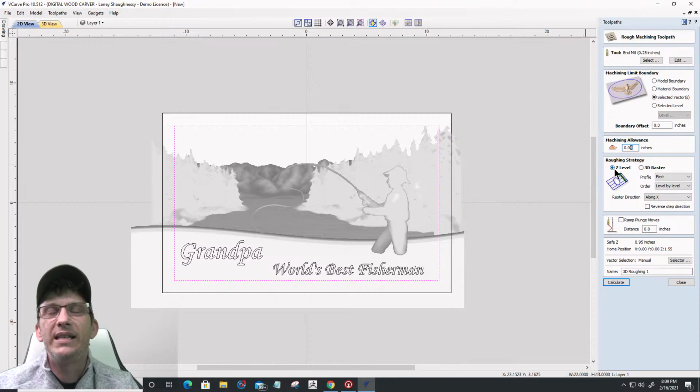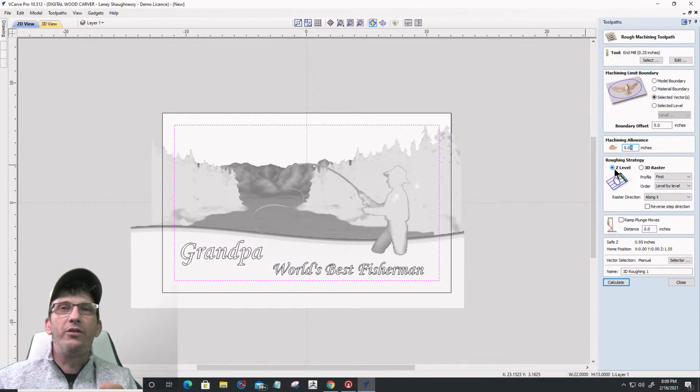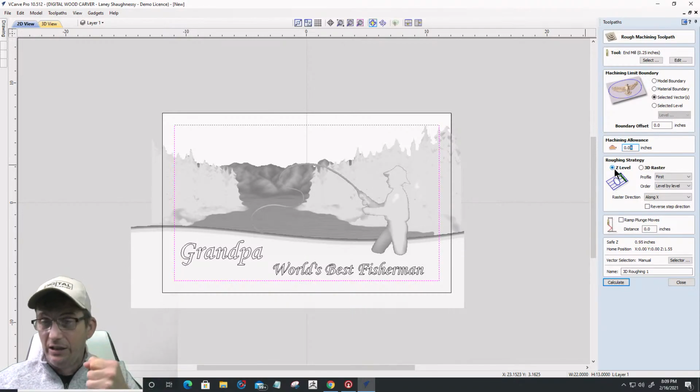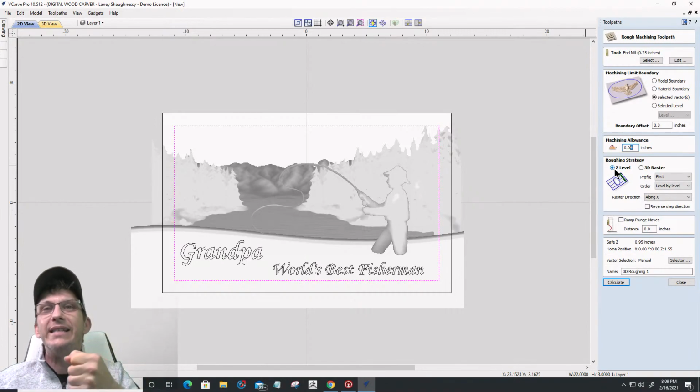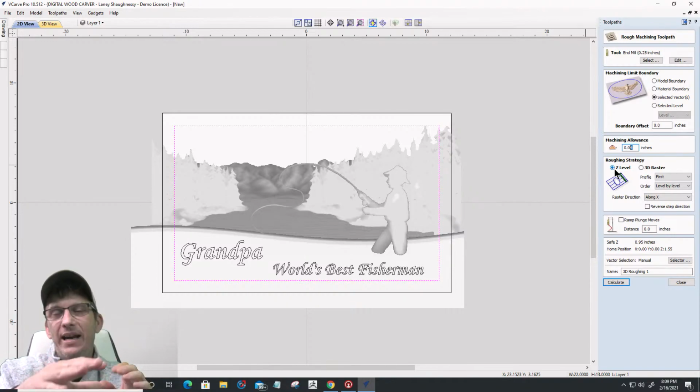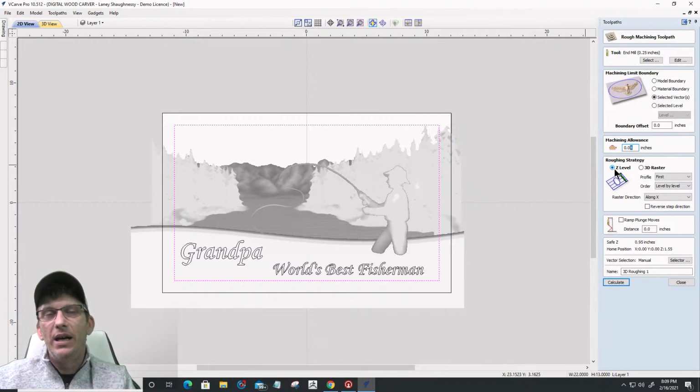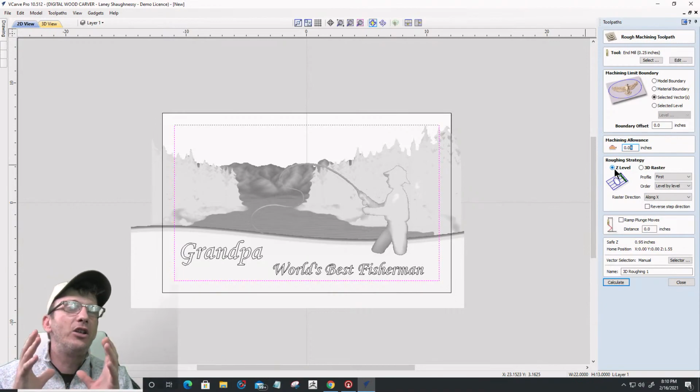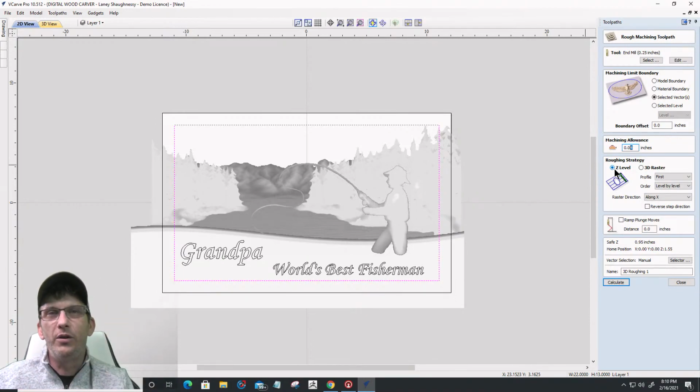I am going to do a Z-level raster. Now, you know, Z-level raster and 3D raster. A 3D raster is literally where my end mill would be doing the 3D cut, leaving whatever allowance I have there, like that 40 thousandths. Some people like it. I have never found a good reason that I should do a 3D raster.